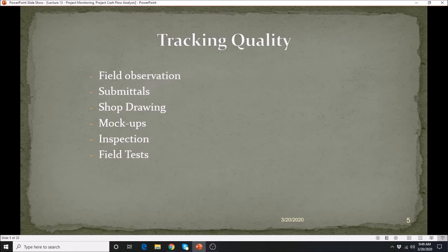Of course, submittals, that's another thing. A submittal is a document which we usually submit to the owner through his representative, such as the architect, for us to get an approval of particular materials or methods that we are going to use for the project. So if that comes late, then it may delay our activities as well. So we need to make sure and plan. There must be a gatekeeper for these, such as the project engineers, to make sure that the submittal has been received and approved, so that we will be able to procure materials or equipment.